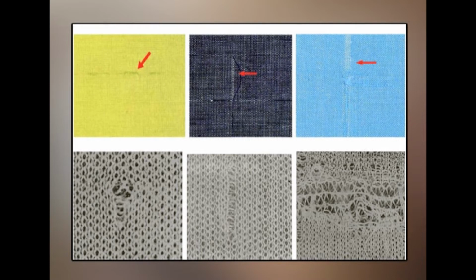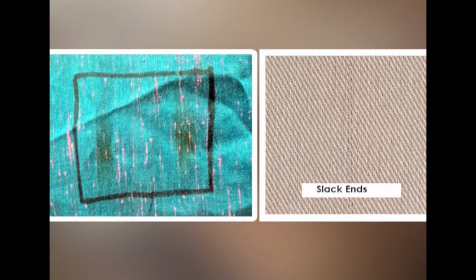While transforming into saleable fabrics, they face problems and get distorted during finishing and other processes, which is shown in the form of fabric faults. Certain faults can be corrected at the manufacturing stage and certain others cannot be mended. A few faults like stains and uneven weaving may be corrected during the finishing stage. Printing may camouflage some surface defects.